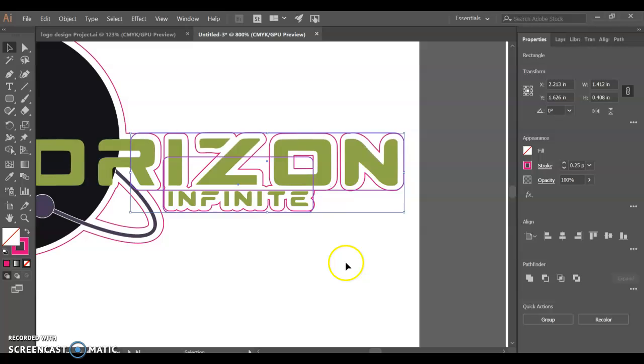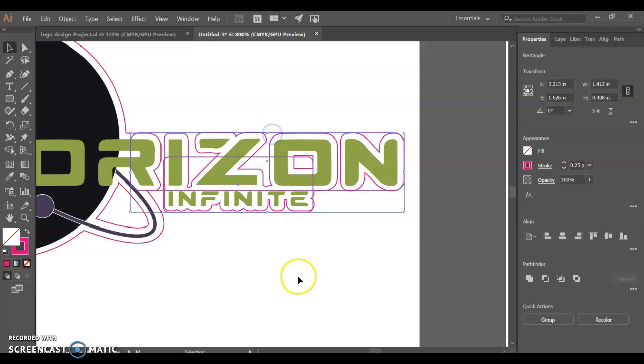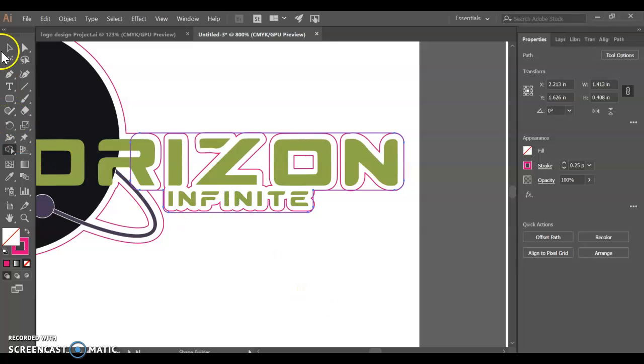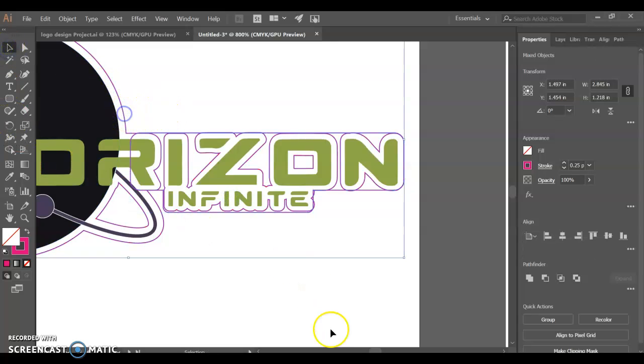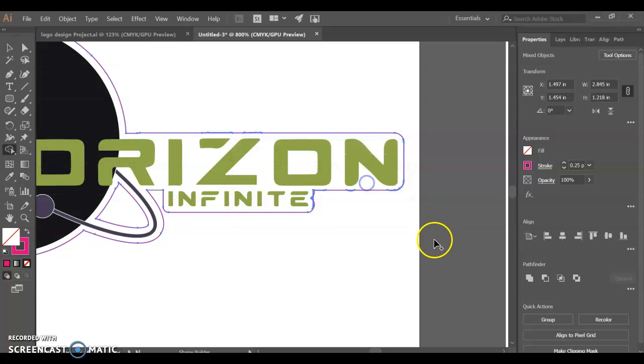Now, what I just did was I selected both the rectangles I drew. Click on this one, and then I'm going to hold shift and click on the other one. This is where Shape Builder comes in really handy. I'm going to use my Shape Builder tool right here and click and drag over to unite those shapes. I can do the same thing by shift clicking on my overall shape that I just created for the logo and using my rounded rectangles and combining some of these shapes. Remember, the overall red shape is what it's going to look like in the end.